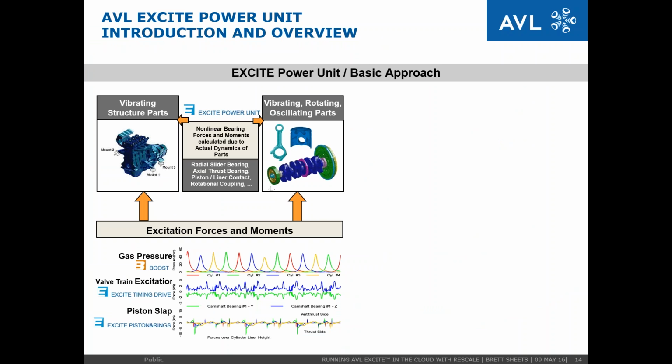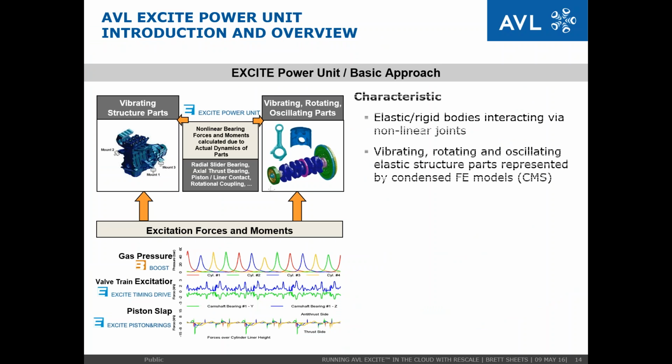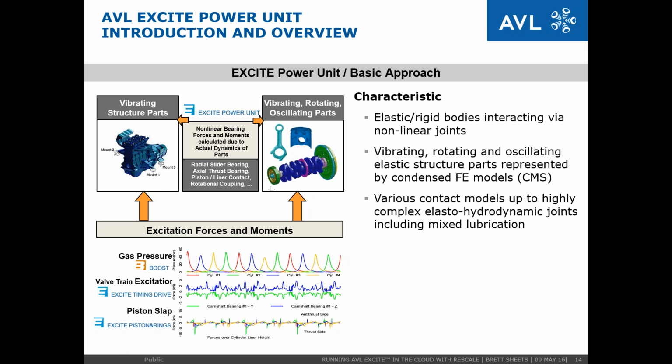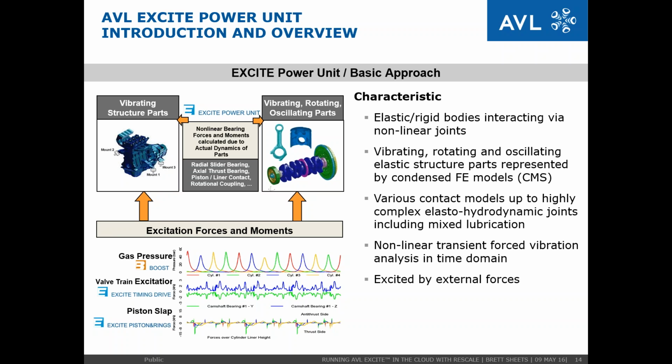What's happening at the fundamental level with Excite is it's using elastic bodies predominantly that are coming from finite element condensations, either using Nastran or Abaqus, and then connecting those up to the bodies through various joints. These joints can be simple nonlinear bearings or complex hydrodynamic joints for looking at the oil film thickness and mixed lubrication. The system is excited by transient forces.